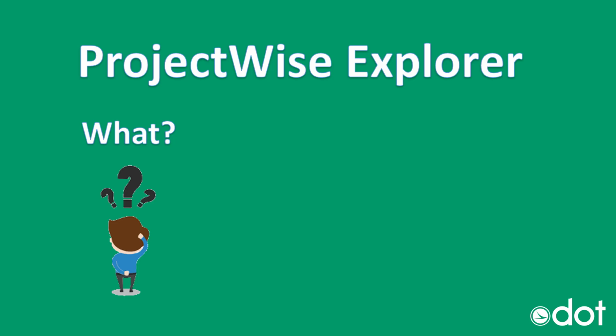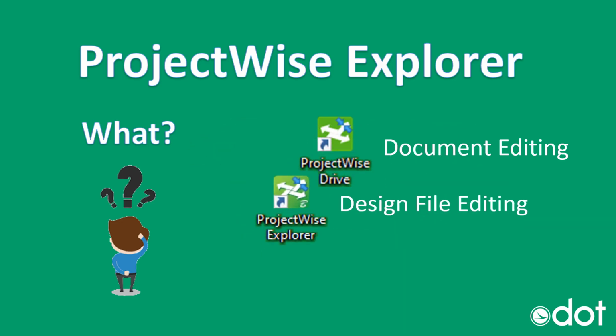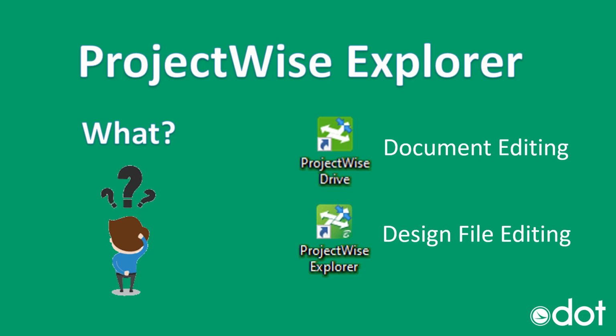As you may know or may not, there are a few different versions of ProjectWise. In this case, we do have ProjectWise Drive, which is one of the newer iterations of ProjectWise. This version is primarily going to be used for document editing, such as Microsoft Office products and those documents. Now, as we go through this class, we will be using ProjectWise Explorer. This is primarily because it is used to access design files and edit DGNs and ITL files and all those other ones that are used to design your projects.